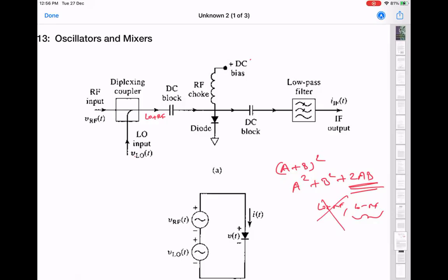So you can think of this that the input signal is creating a current in the diode, but the voltage across the diode, which is what is being taken as the output here, is now no longer linearly proportional to I because it's not a resistor. So V is IR for a linear resistor, but for the diode, you're going to have IR, IR square, IR cube, and so on and so on. So there, the square term is what's giving you the useful part.